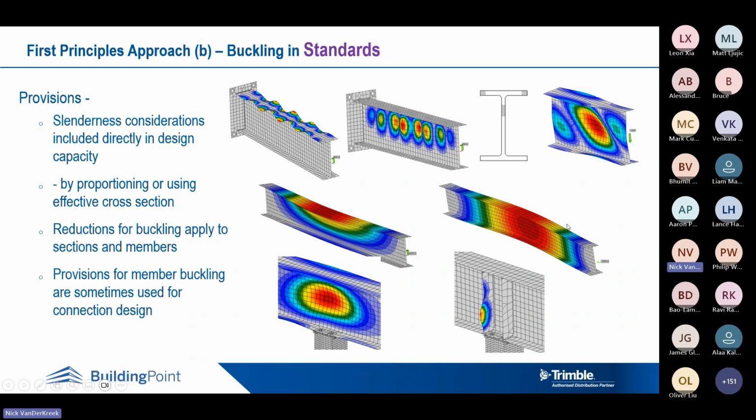including in shear. So this first one on the top left is in bending, local buckling due to bending. In the top flange, also bending, but local buckling occurring in the web in this case, and then shear. Also, of course, you have member buckling, lateral torsional buckling, axial buckling. I'm not really talking about member buckling much today because that's normally something to be considered away from the connections, but it might be something that comes up from time to time.